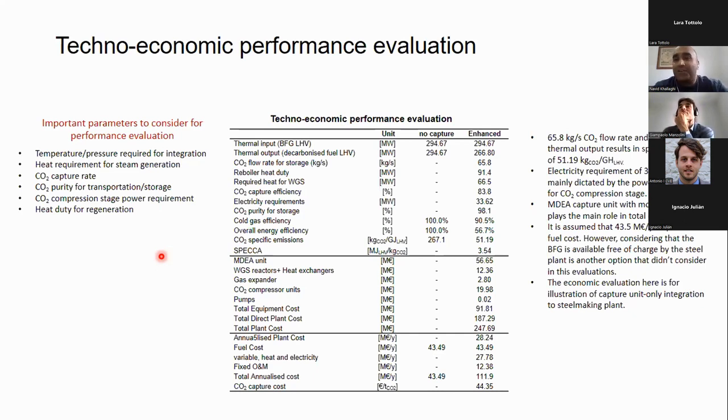Yeah, I have nothing to do with this choice because this is the project that I worked on, and it was defined that we have to use MDEA. This is pre-combustion, and MEA is mainly used for post-combustion, and MDEA is assumed to perform better in this case. So that's the reason we use MDEA. And why not solid sorbents?